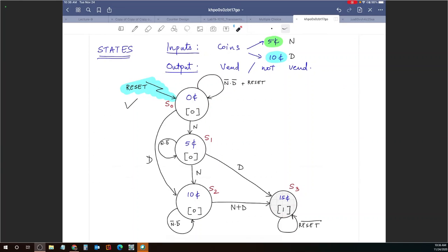And then we went through all the cases. In state 3, that's when your output or vending mechanism should be activated so that the user gets the item. There's a question online: wouldn't we go back to the zero state since the user needs to pay again? No. That's absolutely the same reason we had that assumption, right?